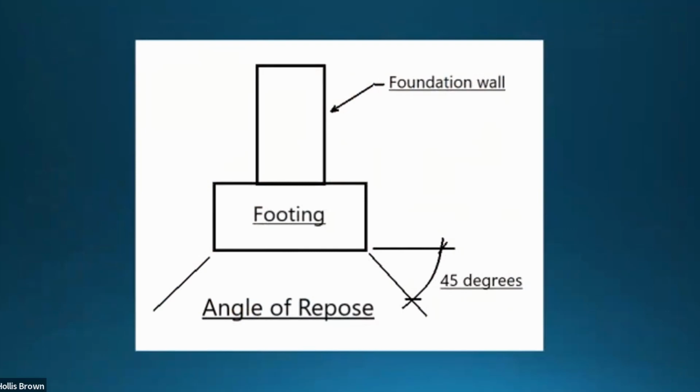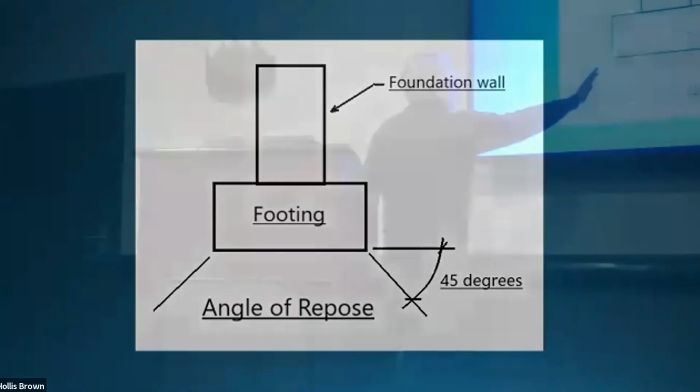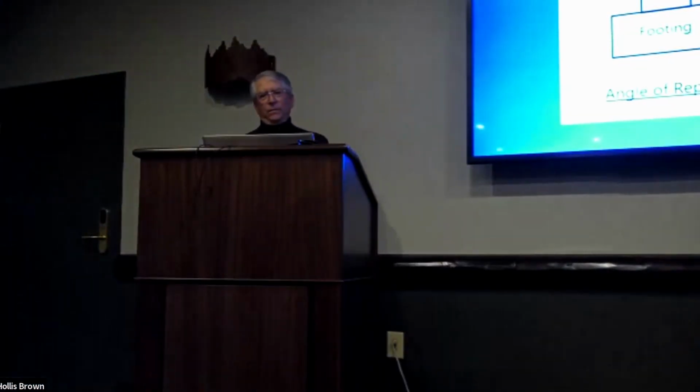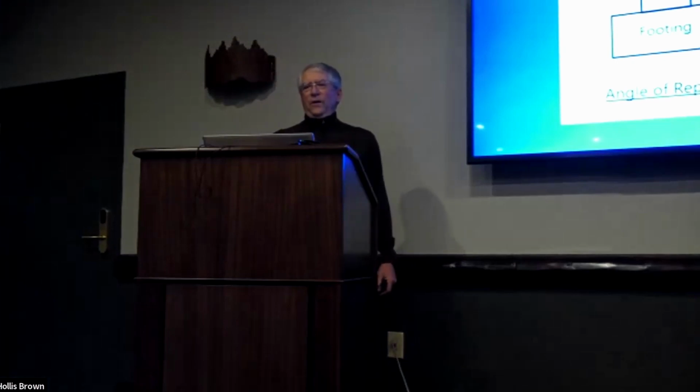Under the footings, and when I say undisturbed soil, there's an angle of repose. You're trying to avoid cutting into that 45 degrees under the bottom of the footing. In reality, every soil or media that you have a footing on has a different angle of repose, so this is going to move depending on what it's on. I'm sure on bedrock, it could be just like that. Sand is going to be way out here somewhere and it would have to be wider. But the 45 degrees is the rule of thumb for that angle of repose that you don't want to cross into.